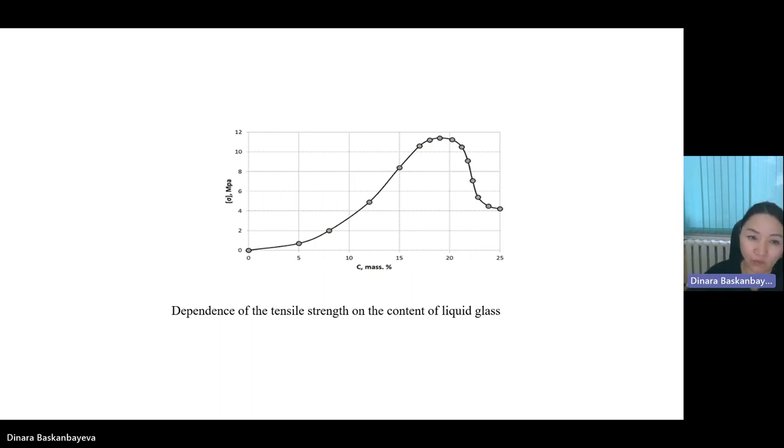The process of hardening of liquid glass is accompanied by the manifestation of adhesion properties to the quartz filler, and is carried out naturally, for example, in air, or artificially, for example, by heating, blowing warm air, drying of the mixture.